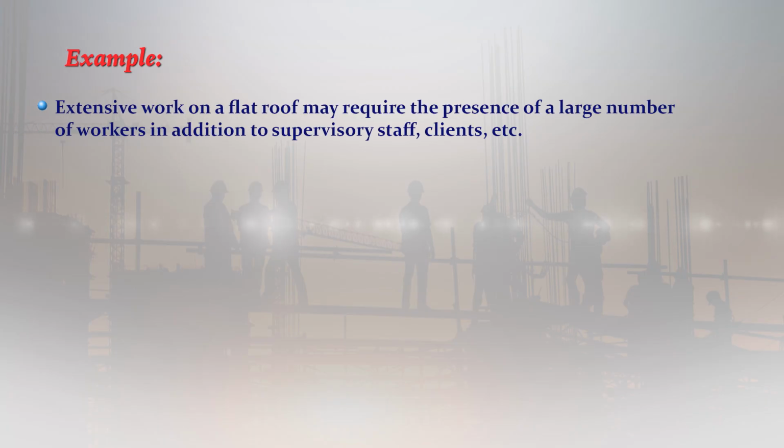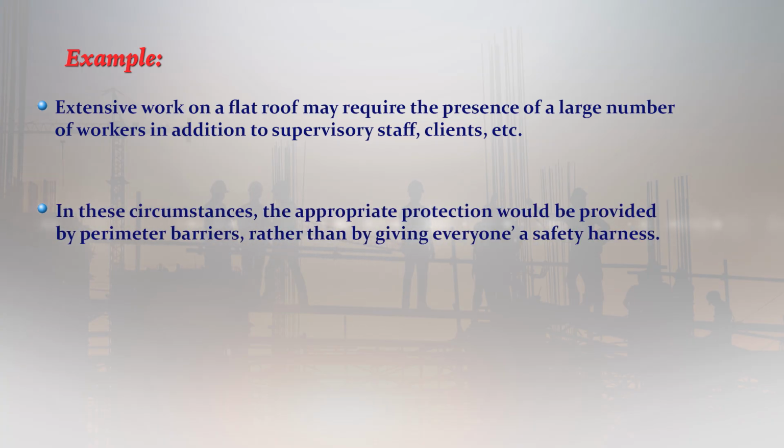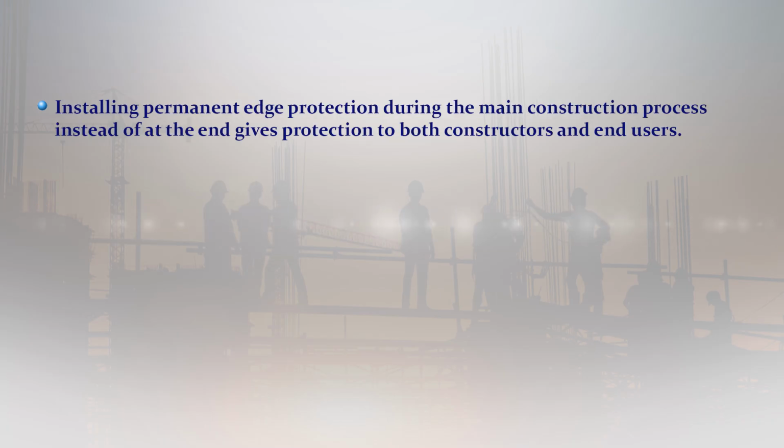passersby. For example, extensive work on a flat roof may require the presence of a large number of workers in addition to supervisory staff, clients, etc. In these circumstances, the appropriate protection would be provided by perimeter barriers rather than giving everyone a safety harness. Installing permanent edge protection during the main construction process instead of at the end gives protection to both constructors and end users.